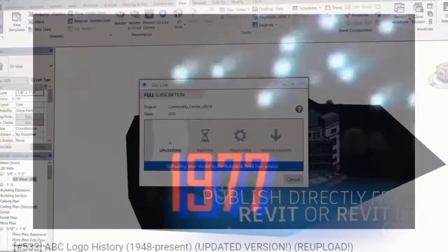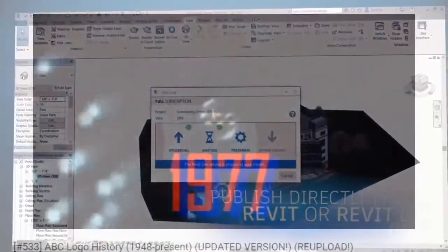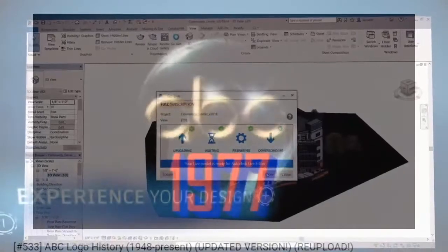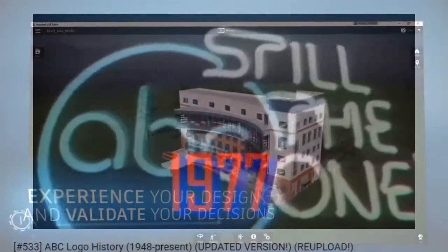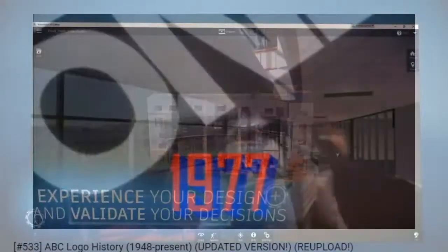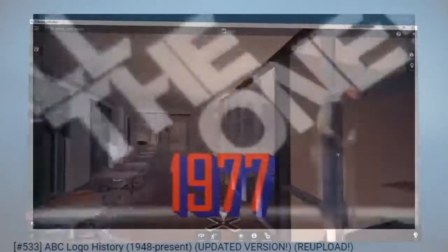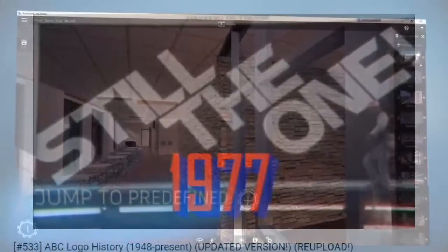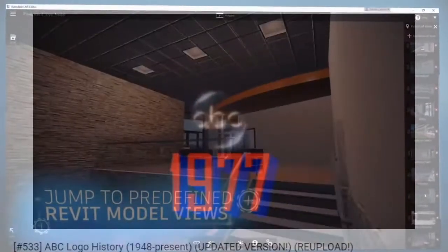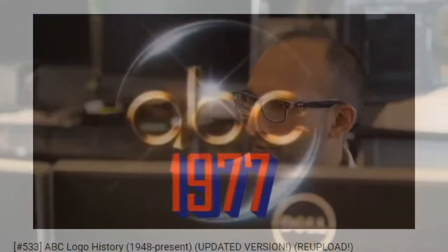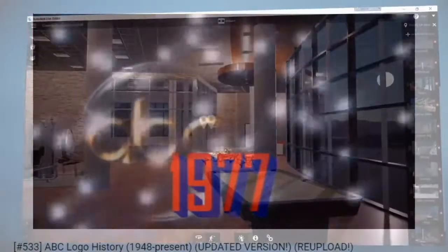Material takeoff creates a list of the subcomponents or materials of any family category. Material takeoff schedules have all the functionality and characteristics of other schedule views, but allow you to get material quantities that make up a component assembly. Let's explore this method with a quick exercise. Open the file C4 Design Floor RVT from the book's companion web page.